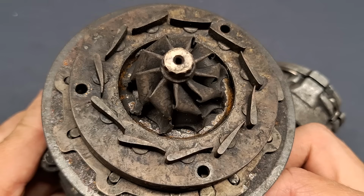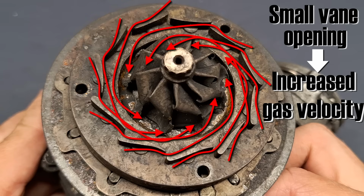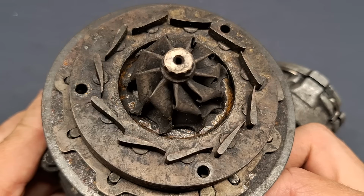At low engine speeds, the blades or the vanes are open just a little bit. This reduces the cross-section of the entry into the turbine housing, and as we already know, if we reduce the cross-sectional area of a passage, the speed of the fluid going through that passage will increase. Increased exhaust gas speed also increases turbine speed, which helps the turbo spool up noticeably faster at low RPM.